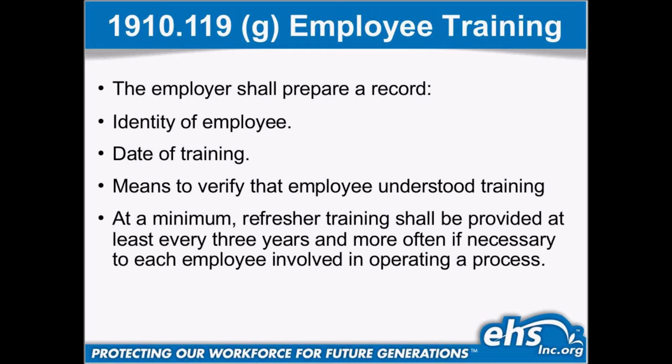Also, you have a requirement of refresher training. It says the minimum is every 3 years, and more often if necessary, to each employee involved in operating a process. The recommendation is once a year, and 3 years is too long. People forget. Repetition actually makes it a habit. The more you go over, the more you review, the more you do it, the knowledge will increase, and people will be less prone to make mistakes.